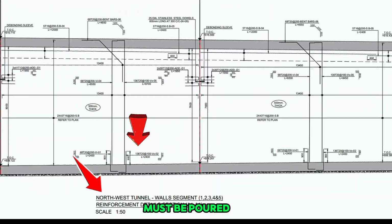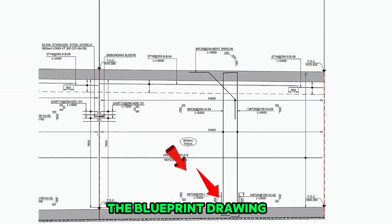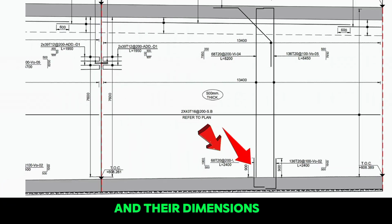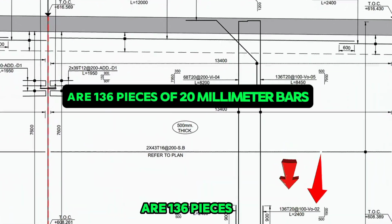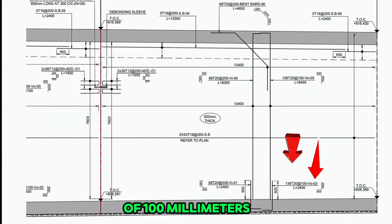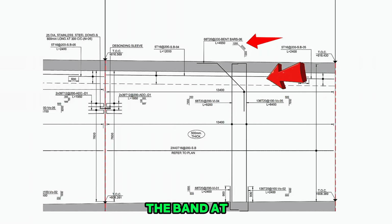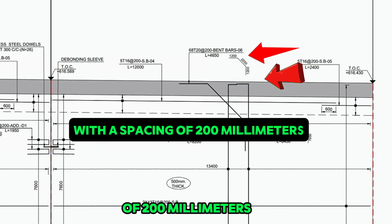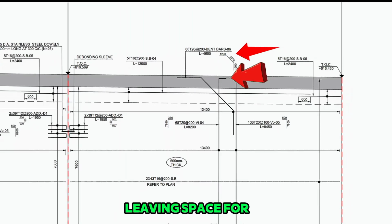This wall concrete must be poured before the tunnel wall reinforcement detailing. We are reading the blueprint drawing of the underpass road tunnel wall, where the starter bars are used first, and their dimensions have been added. The steel bars that will be used on the outside of the wall are 136 pieces of 20 millimeter bars with a spacing of 100 millimeters. Additionally, there are 50 bars at the top with their dimensions provided. The band at the top consists of steel bars of 20 millimeters with a spacing of 200 millimeters, and this band will be added along with the outer vertical steel, leaving space for the top slab cover.